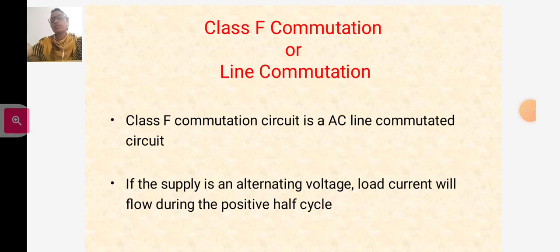The applications of class F commutation are in phase controlled rectifiers, line commutated inverters, AC voltage regulators and step down cycloconverters.